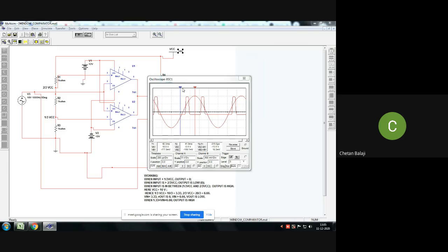So this is the window. Okay, keep it like this. Measure this. Okay, what is it that you are getting here? You are getting 3.6 here. Look at this VA2, 3.6 volts. Perfect. We are supposed to get 3.6 only, right?